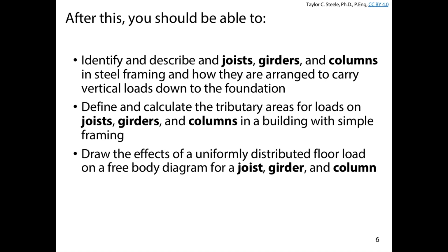You should also be able to define and calculate tributary areas. Anyone heard of the term tributary area before coming to this course? Anyone from St. John here, like UNBSJ for the first 2 years? Tributary area? Yeah, no? No? Okay, so a new concept for the course, that's fine. You should be able to define and calculate those for joists, girders, and columns. Basically, the tributary area is how much floor area one element is responsible for supporting, and we'll talk about that today.